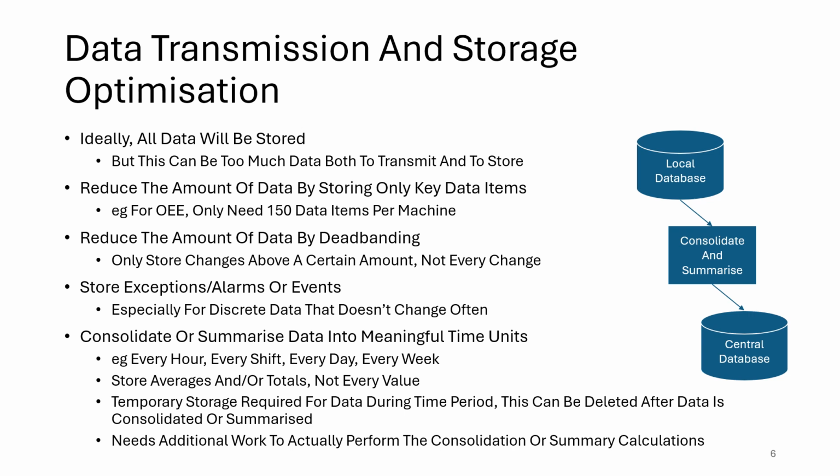You also need to think about storing exceptions or alarms or events, especially for discrete data that doesn't change very often. This can help you understand what's happening with the machine and again have more context around events and machine behavior and performance.